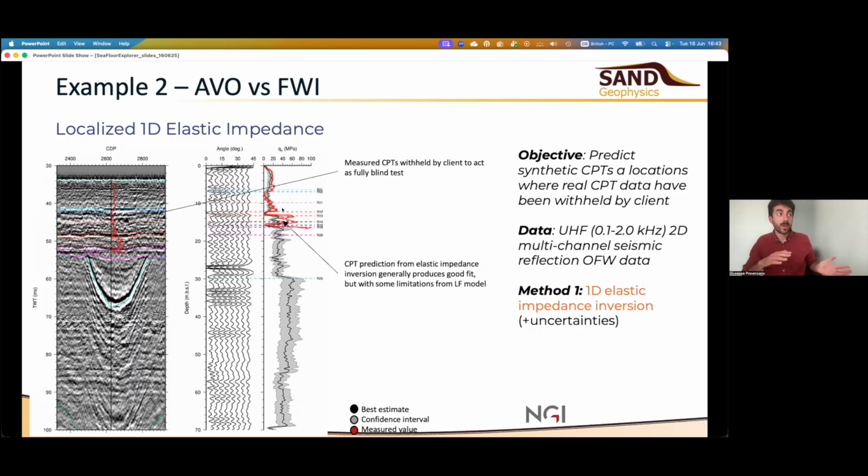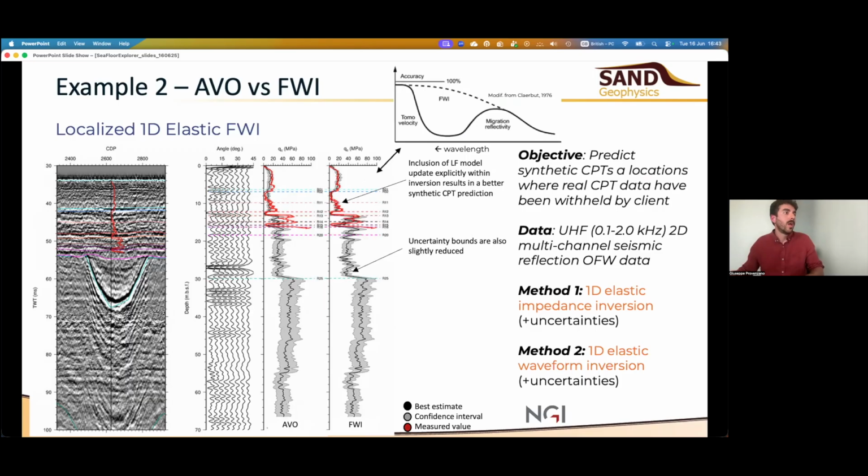Of course, full waveform doesn't give you directly the CPT parameters. There's then a machine learning tool in between, but the quality of the input data is what determines then the quality of the prediction. So generally, we haven't got a bad fit, but we don't quite get quantitatively the increase in tip resistance. If we use full waveform inversion, you see the predicted model kind of locks into the ground truth data, and this is precisely